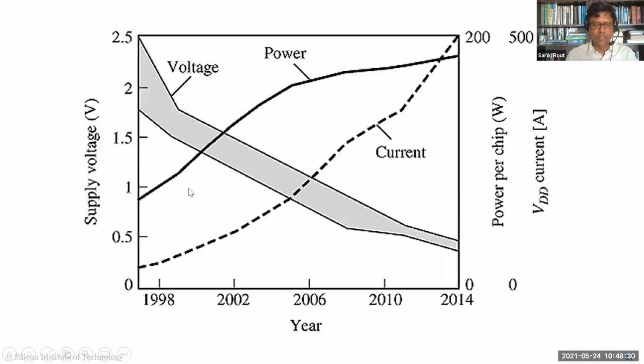So this is another trend, showing you how the power and voltages are scaling. For example, you can see around 2004, the currents required were scaling much faster than the voltages were scaling down. You'll see later on during the course, and some of you probably already know, especially for digital, it's purely dependent on the voltage. If you lower the voltage by half, your power will scale by the square of that. In analog, it's a little different. It's dependent on both voltage and current, because you can control both. But in digital, it's pretty much the voltage because it's half CV squared.